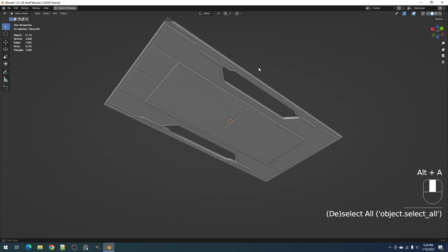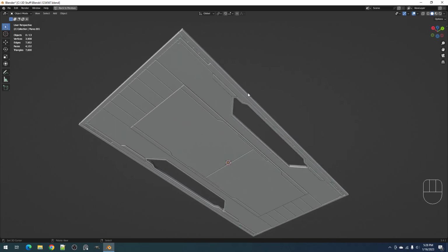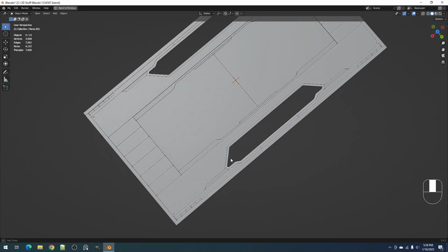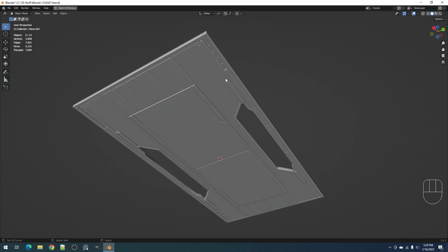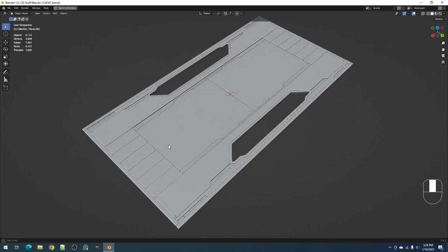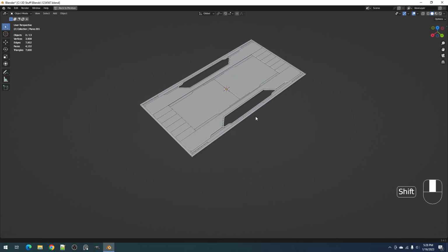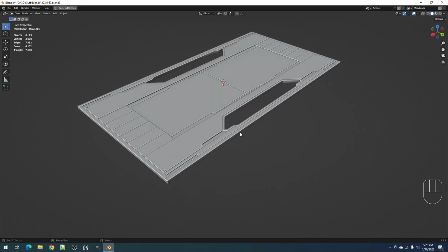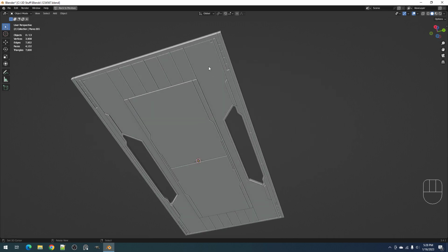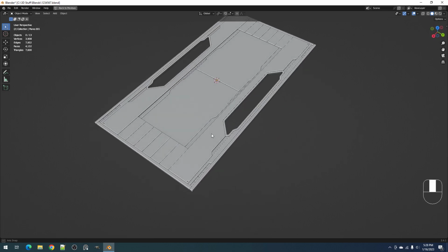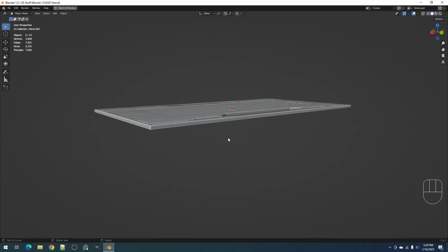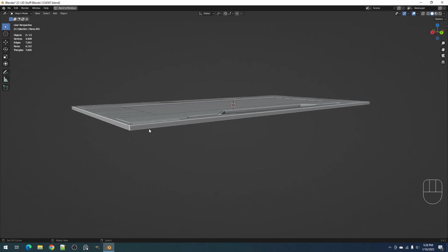The disadvantage in using this technique is because of the nature of the design, the cut will be replicated on the other side of the model. But of course, when you're retopologizing and creating a bake mesh for this, you don't have to include the faces for this part here, and just include the top faces and this one here.